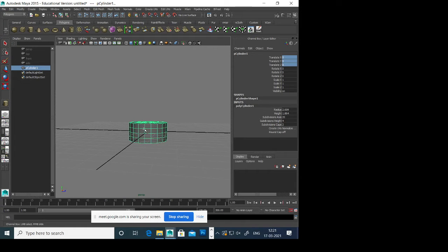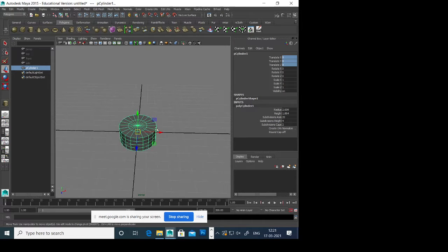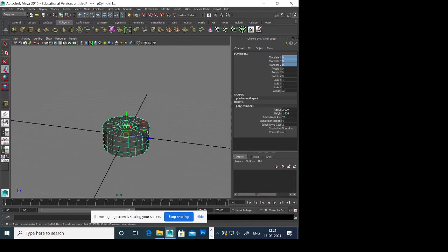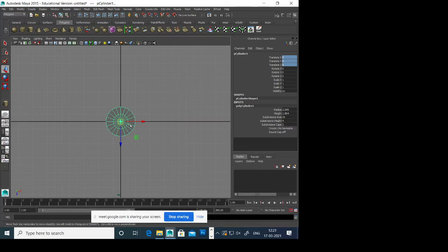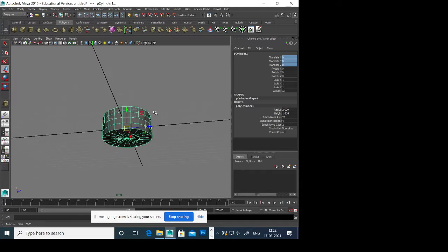Suppose I want to snap this, it should be above my ground, this grid, right? Whenever you model, it should be above that. In Max, you have to check and snap it to the grid. So in Maya, it becomes really handy and easy. Press X, your W gizmo will come, this move tool, spacebar, go to any front or maybe side, any of these, or perspective.